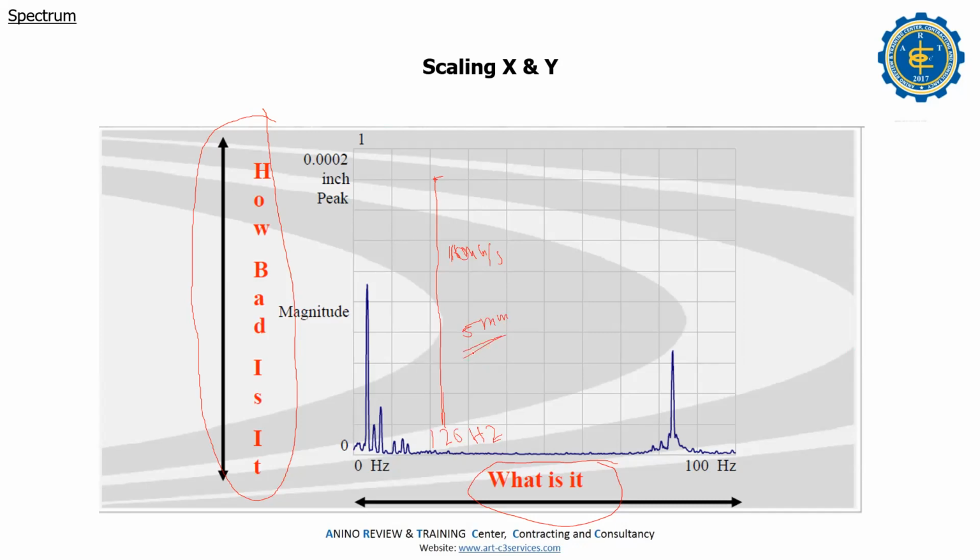But what is your experience? What is the highest mm per second you have gotten? Sir, sometimes we have a critical fan, so sometimes we get 25 also. Okay, 25 millimeters per second.